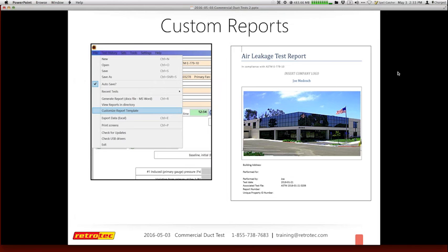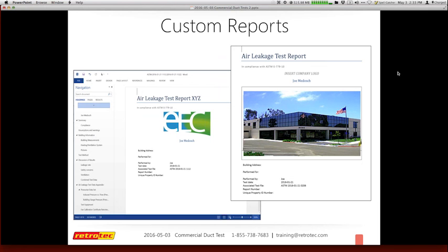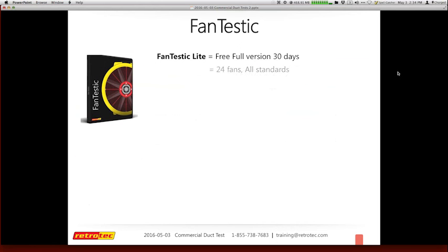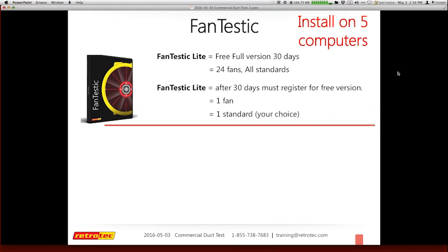Some other things we talked about earlier were comparisons, and that is how to change the plugs or the orifices. There are no tools required. It actually changes in a matter of seconds. Some systems have tools or wing nuts or a variety of stuff, and can be a little cumbersome if you're not happy with the flow that you have. Many of these ranges overlap somewhat, so you're not always held tight by a single range. Then your gauge will tell you by showing 2 dashes that you need to alter your orifice, because it cannot get the results needed from the fan.